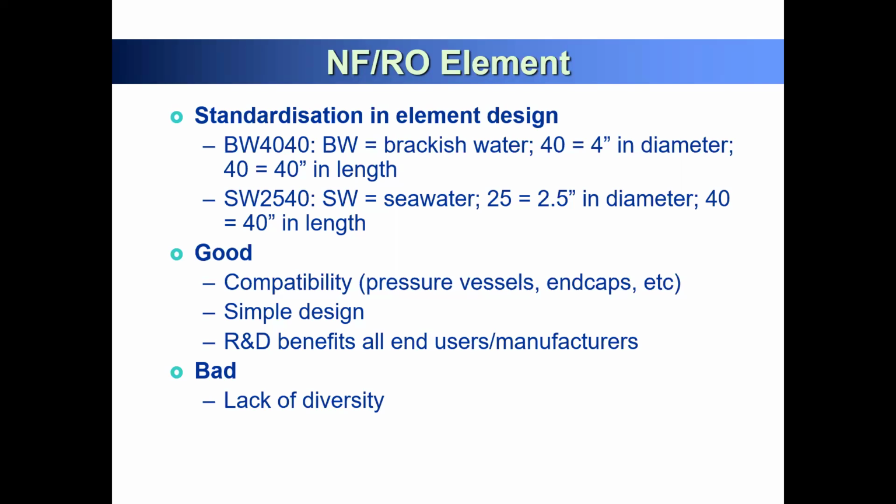So luckily, our membrane business has better collaboration than the mobile phone business. They have a standard 10 centimeter pressure vessel and 5 centimeter pressure vessel. So we can buy any different company's membrane module with the standard diameter. The length is also 1 meter.